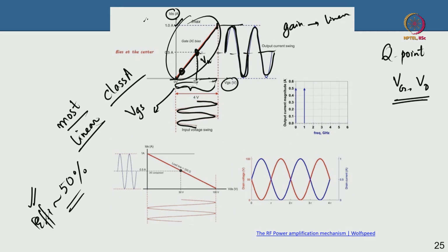And that is very important for wireless communication, specifically for handheld gadgets like mobile cell phones, where you depend on the battery, and the battery's lifetime directly depends on the power added efficiency of the power amplifier, which is the most power hungry block on the circuit. So people tend to bias the devices at higher classes, class C, class J, etc., where you get significantly enhanced efficiency at the cost of non-linearity, and people then try to mitigate that non-linearity using approaches at the circuit level, such as a pre-distortion block.